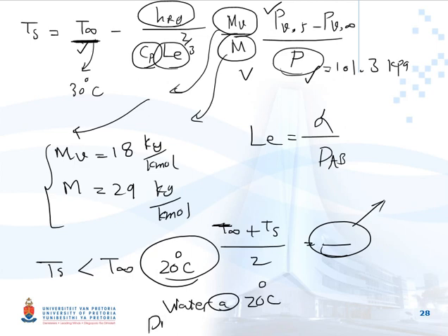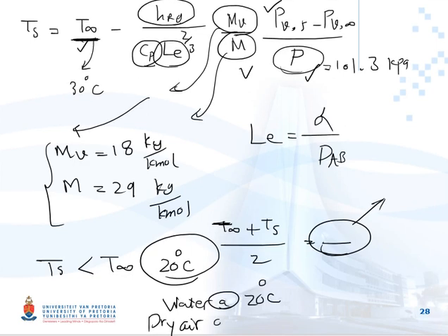But dry air we read at the average temperature of the hot dry air and the surface temperature, which is 25 degrees here. What information from water do we need? hfg. So we go to the table and read it. hfg is equal to 2454 kilojoule per kilogram.